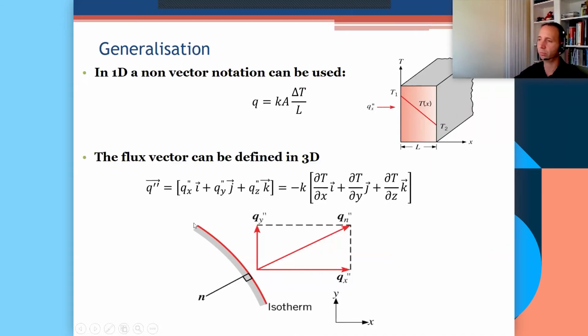We did say that, sometime I'm going to give the definition Q or Q double prime. The difference is just that you need to multiply this by the area A to get the rate of heat transfer. Q double prime is defined as minus K times the gradient of temperature. The gradient of temperature in 3-dimension is written like this. So it's the rate of temperature change with respect to X, to Y, and to Z. Temperature, therefore, is a function of X, Y, and Z, so that the derivative must be written as partial derivatives. Okay.